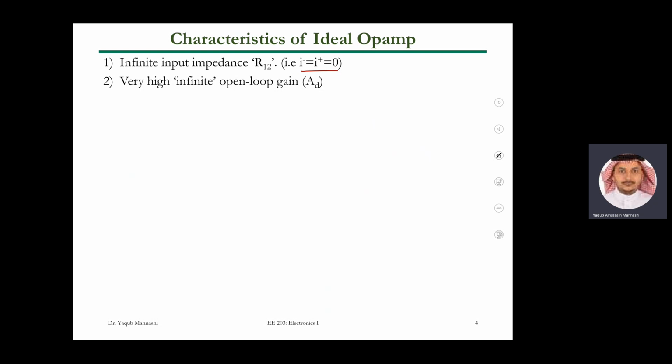15 maximum. It cannot go beyond the 15, right? This is the maximum. I give you, you cannot take more than what I give you, right? You cannot get more voltage. From where would you get that much voltage, right? There is no way. So it will be saturated to 15 volts. So if you have 1 and 0, this one is expected.